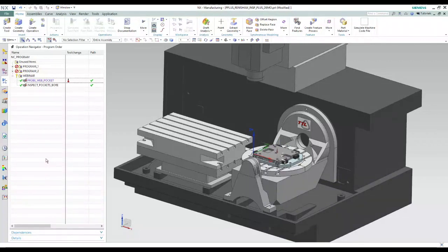Okay, so we've just seen the support and the use of the machine resident numeric cycles of Probing Plus. Probing Plus also supports the use of third-party probing software such as Renishaw Inspection Plus. Here I have another NX installer machine that's been set up to support the appropriate version of Renishaw Inspection Plus. Different machines and controllers require specific Renishaw software packages, and so each of our Probing Plus software versions are tailored to support the differences between the cycles.